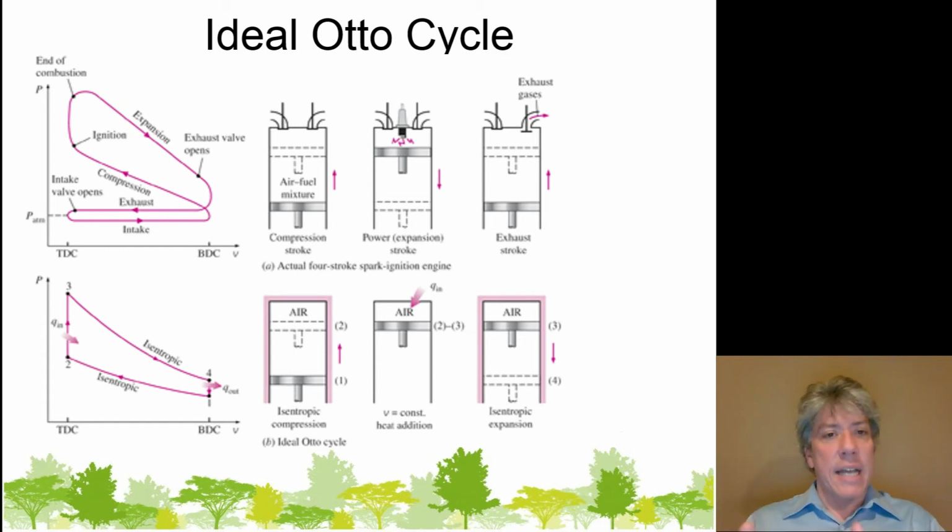So in our idealized system, we're going to completely neglect the exhaust and intake stroke, because the whole point of those strokes is to get a fresh charge of air. Basically, it's to cool the air back down. Right, that's the point. And since not much area is enclosed by that exhaust and intake stroke, we can safely neglect it.